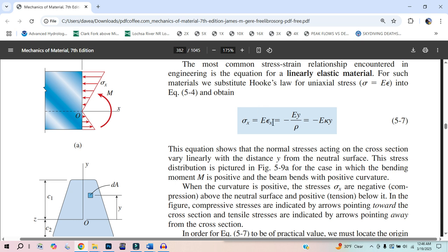So how do you relate this tiny number to this one? It's linear. If I halve this number, then I halve this. If I double this, I double this through that linear range. So this is an equation of a line. You know what I mean? It's y equals mx plus b, and the y-intercept is going right through the origin. This is a tiny number, and this is a fairly decent sized number. And so this is a huge number, the modulus of elasticity. But hell yeah.